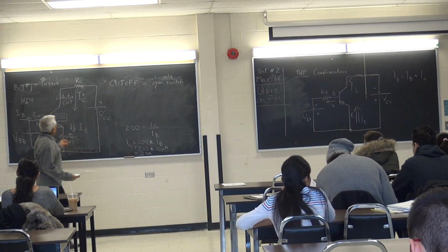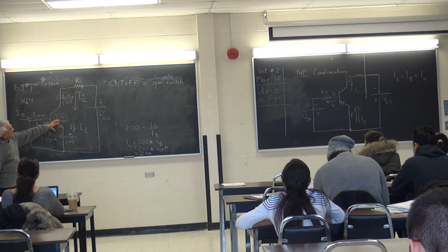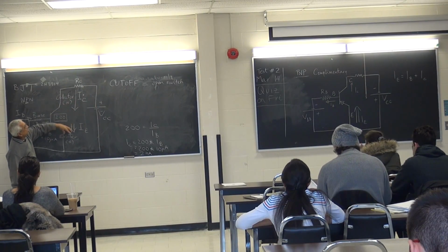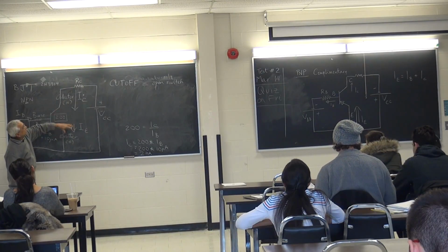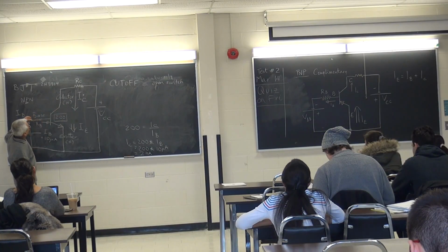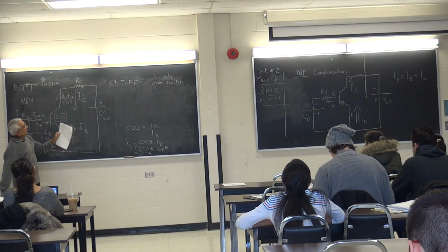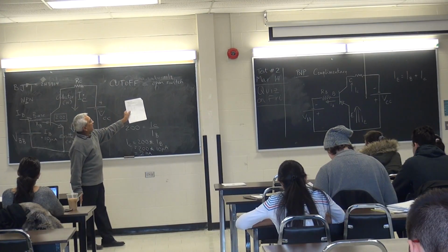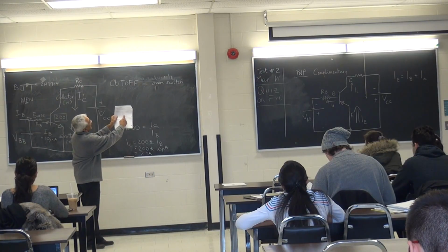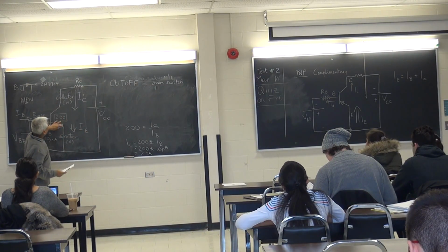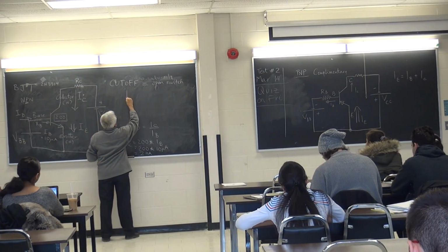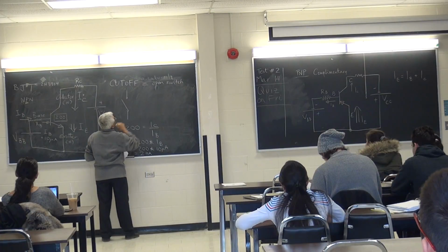So when would a transistor act like an open switch? An open switch basically means that there is no current flowing in the transistor. And the current in the transistor is IC. And IC cannot flow if there is no IB. So that's what figure 12 shows. It shows IB is equal to 0, which results in the transistor collector to emitter, here's the collector, here's the emitter, behaving like an open switch. So that's what we show as far as the transistor is concerned.